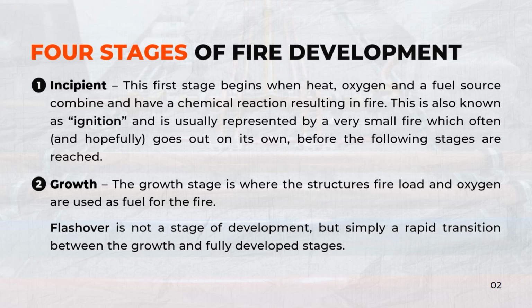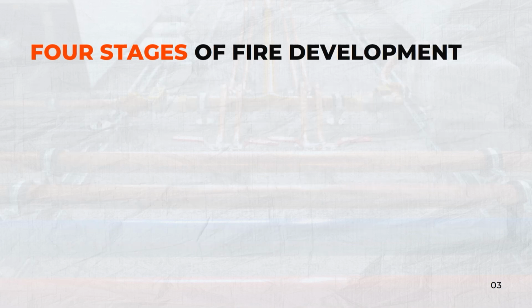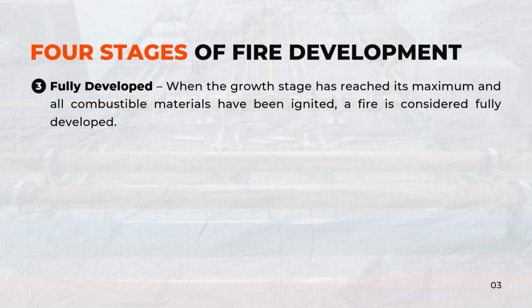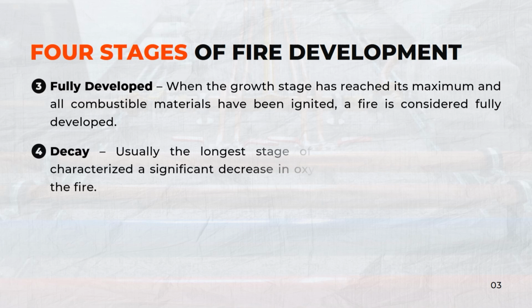Second, growth. The growth stage is where the structure's fire load and oxygen are used as fuel for the fire. Flashover is not a stage of development, but simply a rapid transition between the growth and fully developed stages. Third, fully developed. When the growth stage has reached its maximum and all combustible materials have been ignited, a fire is considered fully developed. Fourth, decay.